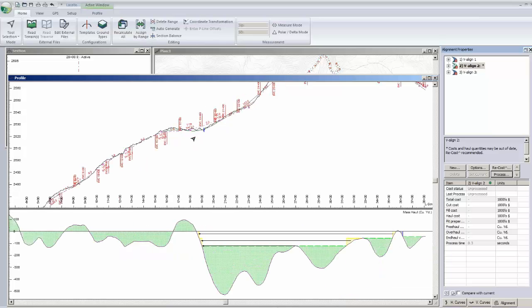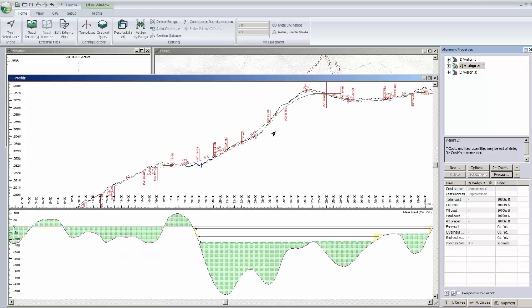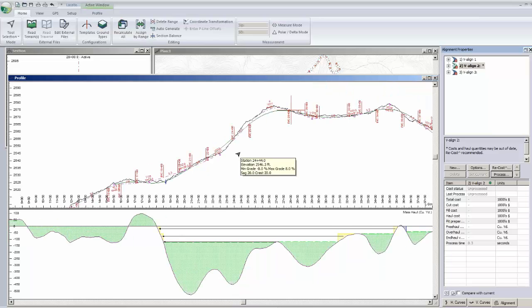So when you have a situation where you've got lots of things that you need to avoid, maybe utilities, you need to tie into driveways or intersections, and you want a certain design speed, it just may not be possible, and this will tell you pretty quickly if it is, and you'll have to relax that constraint to get a solution. So rather than fiddling around with the alignment for hours, this will tell you quite quickly if something is feasible.